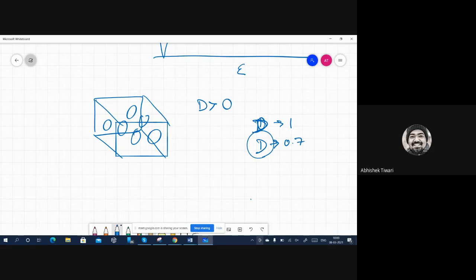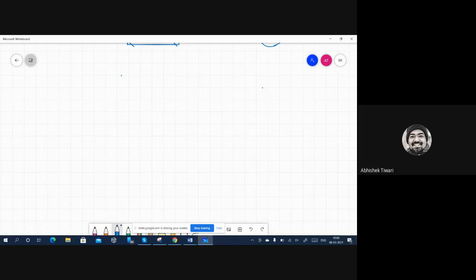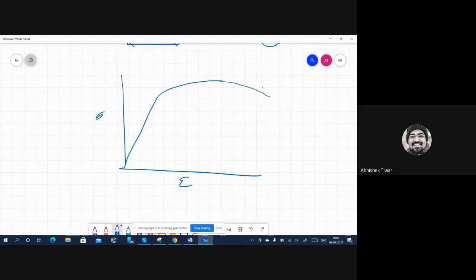So do you think 30% of this reference volume element is sufficient to take the load? And it is also realized in our stress strain diagram of a tensile specimen that the stress increases, goes to the maximum, and then starts dropping. But you don't see a stress strain diagram which usually goes like this till the stress becomes 0 and then it fails.